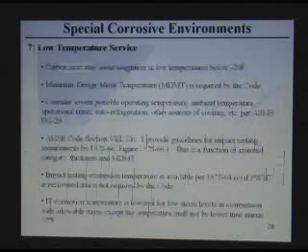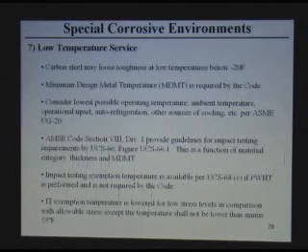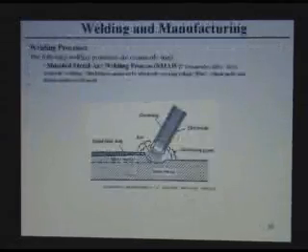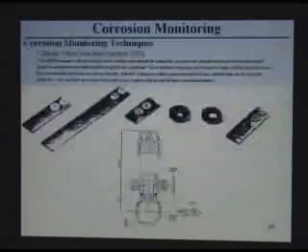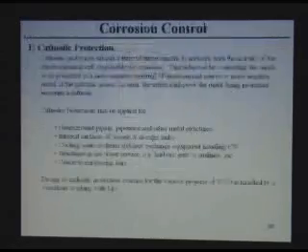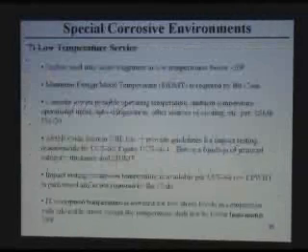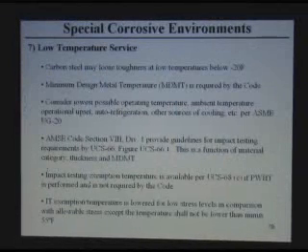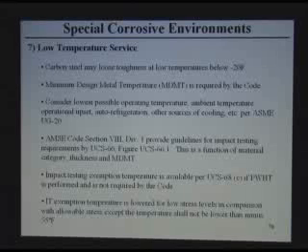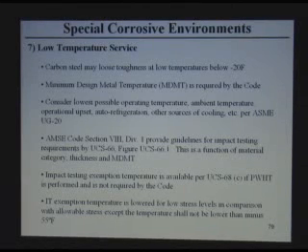Okay. Now we go to low temperature. As I mentioned before, you lose ductility with low temperature. Below minus 20 degrees minimum design temperature, you should be careful using carbon steel because it loses ductility.